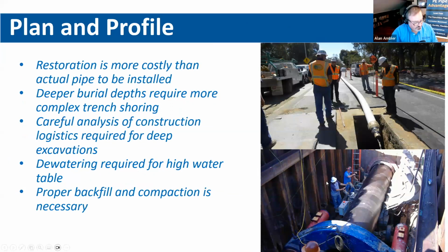So we'll spend a little bit of time with deeper installations. Now we get a lot of that question itself: segmental pipe in a 20-foot stick, 13-foot stick, 15-foot stick, whatever it might be. Sometimes it's easier to get a trench box that's more the length of that size to work with that segmental installation. Now the trench box, the hole, and any type of shoring that you use, even as we go deeper from what you're seeing here with the steel sheet pile, the deeper the installation, the more costly and more expensive that shoring becomes.